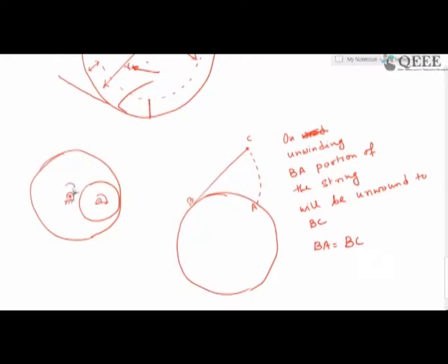So both of these gears will have the same sense of rotation, and therefore the sign flipping doesn't occur in the case of internal gearing.